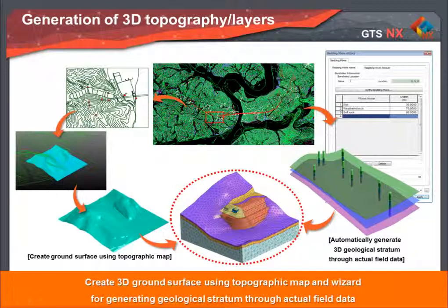It is also equipped with a bedding plane wizard that enables us to model uneven soil strata with ease. We can directly utilize our soil profile by entering the boring log data for different locations. The program will then automatically extrapolate the changes in soil levels between the points to allow us to generate our soil layers.